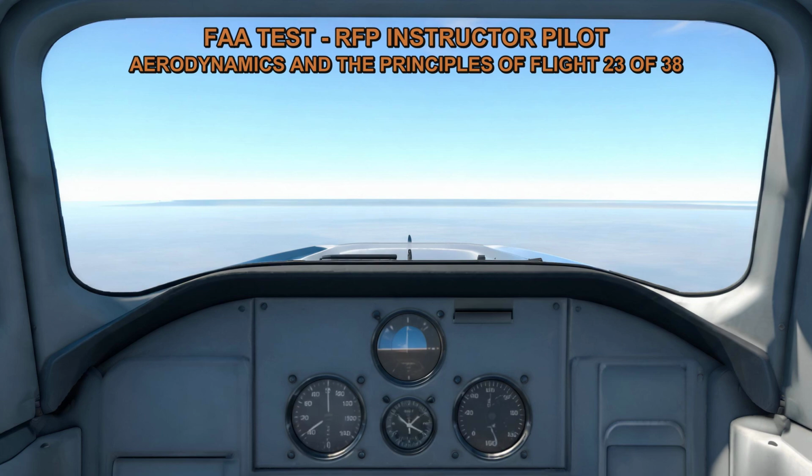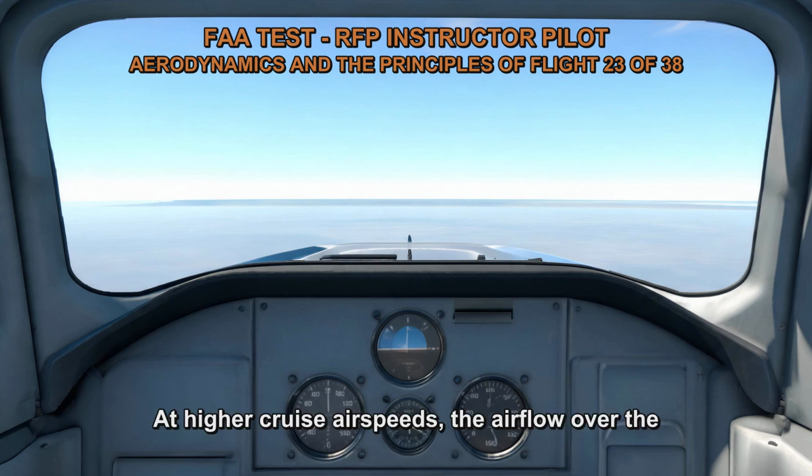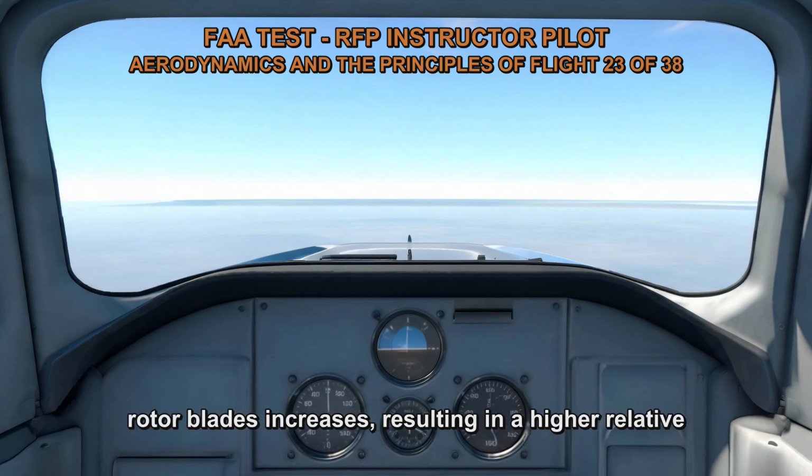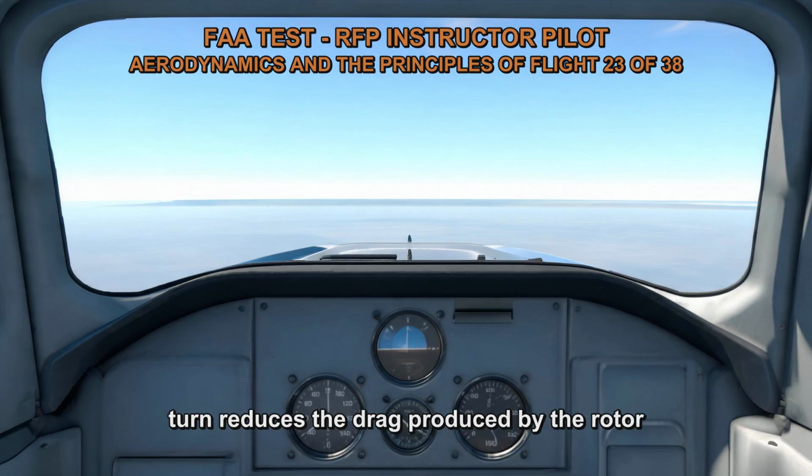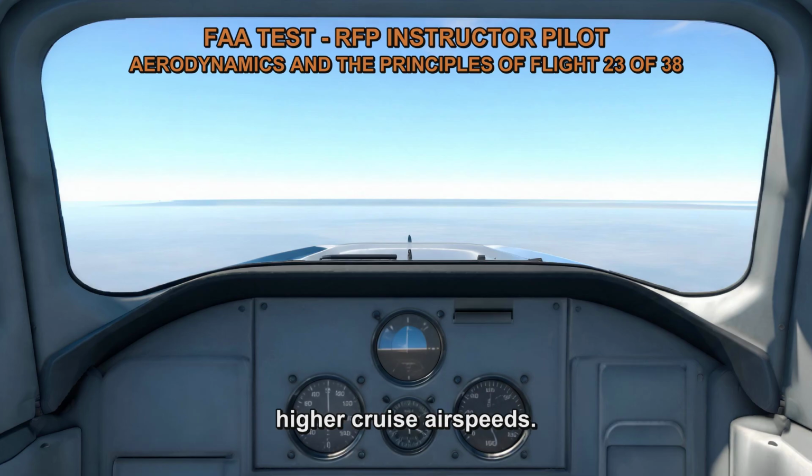the rotor system. At higher cruise airspeeds, the airflow over the rotor blades increases, resulting in a higher relative wind speed. This increased airflow helps to reduce the angle of attack of the rotor blades, which in turn reduces the drag produced by the rotor system. As a result, the rotor drag decreases at higher cruise airspeeds.